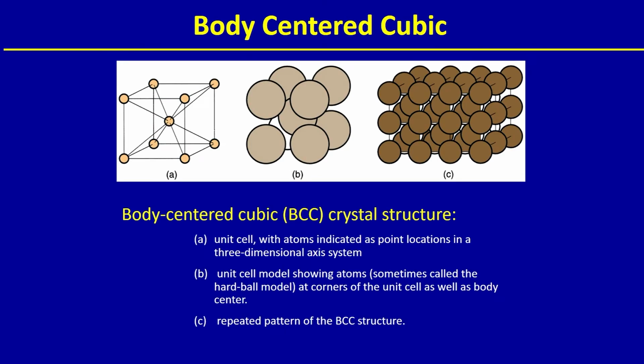The next higher order structure is known as the body centered cubic structure. You have learned simple cubic. Now, let us put atoms not only at the corners of the cube, but also at the center of the cube. That is why it is called a body center, because it has an atom in the center of the unit cell, the center of the body. That is the geometrical way of looking at it. Actually speaking, atoms will be arranged this way. You can easily draw this unit cell the way we have done.